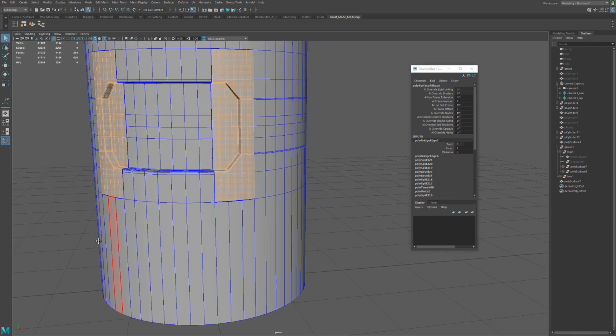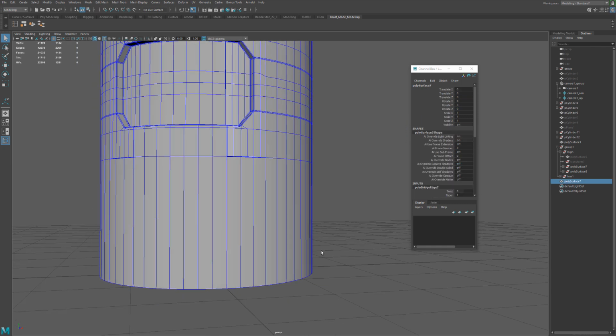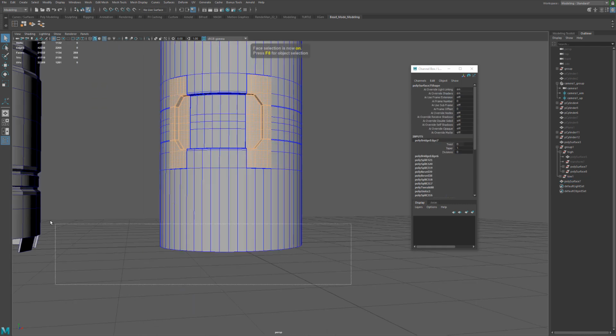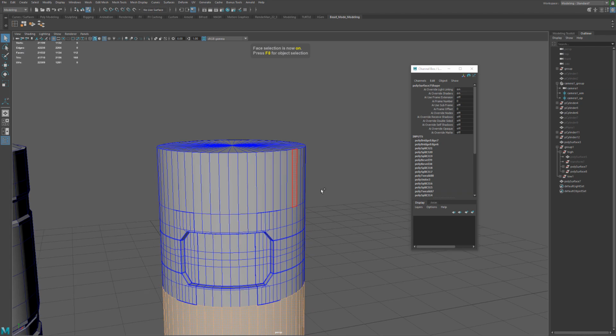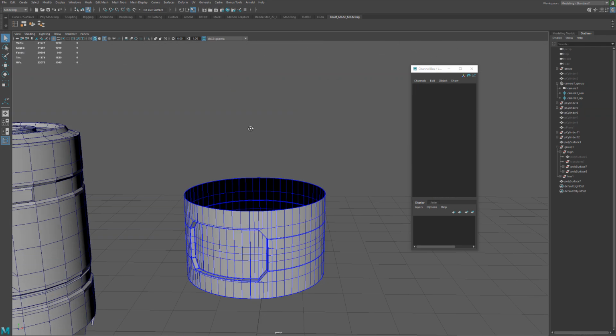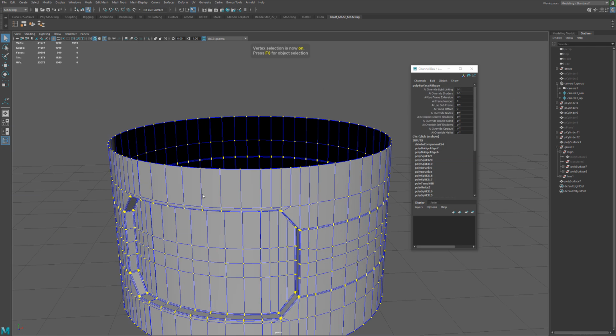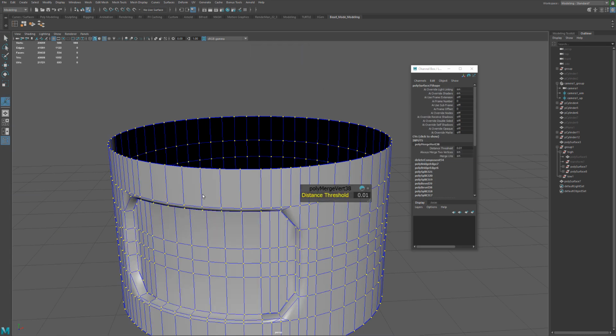this is going to cause that pinching that happened here, right? So what I'll do here is take this and then take this guy here, hit delete. And then I'm going to take all my verts, select, merge, and put this down almost to 0 and give it the lowest tolerance possible.